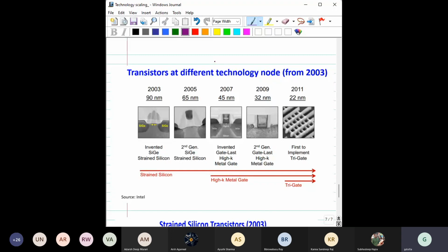No, physically they are improving, but not only by gate length. There are different other techniques also associated. For example, now transistors are not planar. Transistors are 3D, FinFET. This is the transistor you used to see, but can you recognize that this is also a transistor? See here, this is the gate. Here transistors are now like a fin. You understand a fin, right? This is a fin, and the gate will come and go over it like this. This is the source, this edge is the drain.